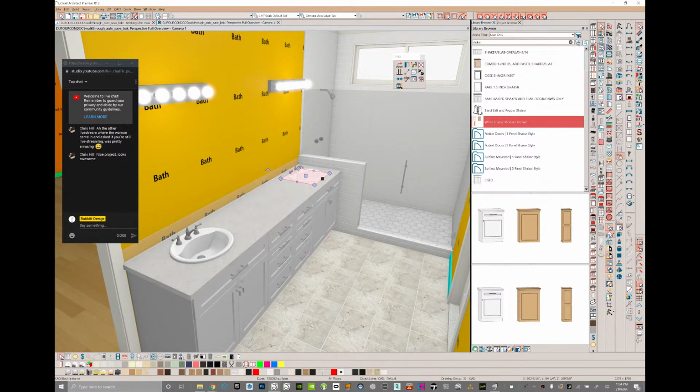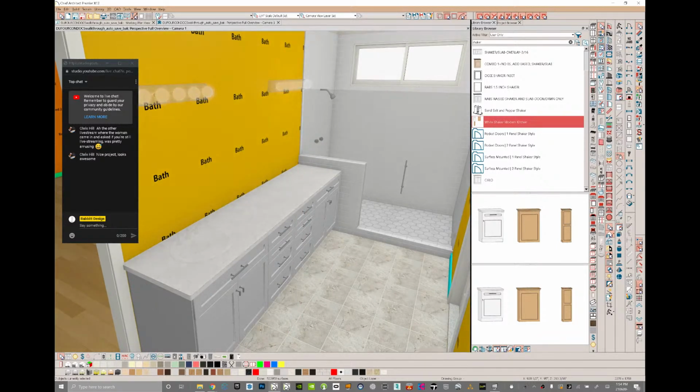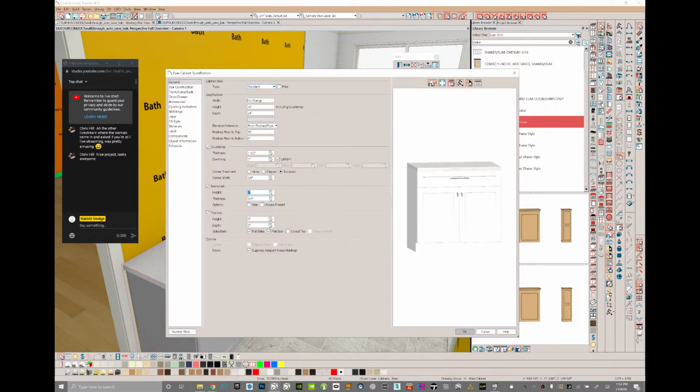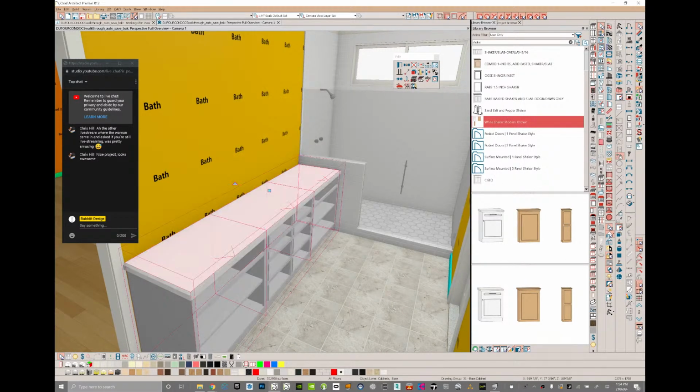Here we go. And these sinks are just atrocious, so we're going to get rid of them. And in fact, these light fixtures are pretty bad as well. Let's go ahead and get a backsplash back on these. Let's make it a 5-inch splash. Why not? In fact, we could do a 6-inch splash, make it match that line of the wall there. It actually looks like it's matching at 5.